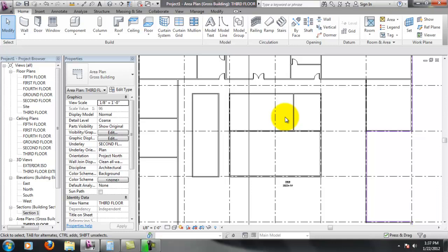and the code states that you need 2 toilets for the first 50 people, and then 1 toilet for each 50 after that. The code also states that you need 1 sink per 40 for the first 80, and then 1 sink per 80 for the remainder. They word it kind of funny, especially if you have a large amount of people. You could go ahead and just say that I need 2 for the first 80.